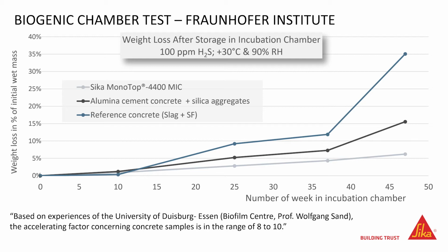The reason is that approximately 75% of the mortar surface, due to the presence of silica sand, does not stop the proliferation of sulfuric acid. The last curve, 100% calcium aluminate mortar, shows when the whole matrix, cement and aggregates, is made of calcium aluminate. The degradation is actually very low.